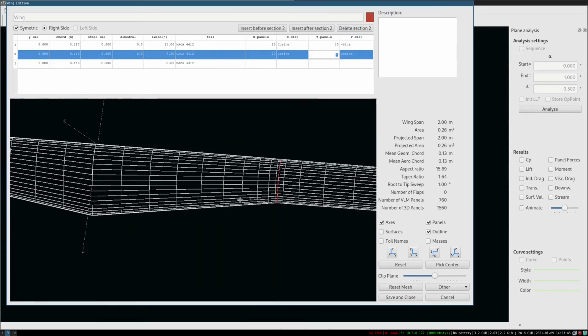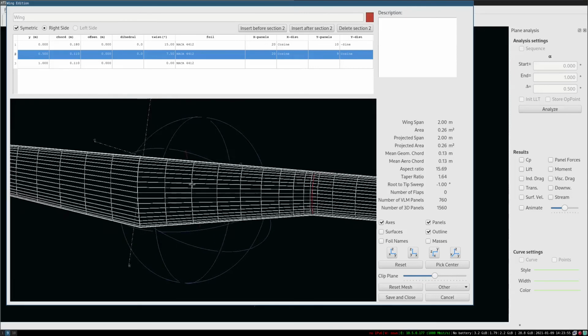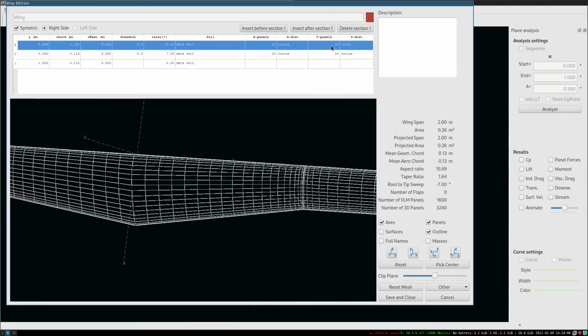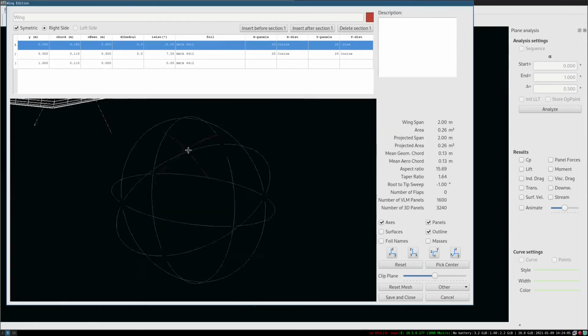The thing I will point out is that the stability calculations, when you come to do those, the matrix size that you're solving is directly proportional to the number of elements that you have, so you do need to be quite careful how you size the number of elements that you use. This is, for now, fine.